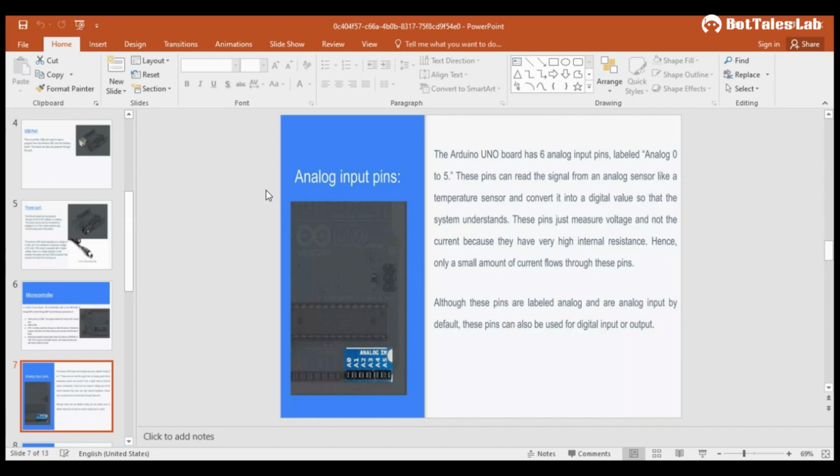input. That is, some sensors are there, like a temperature sensor or gas sensor, which provide output, or you can say which provide data in terms of some particular value, in the range of 0 to 255, in the range of 0 to 120. While other sensors are there which read data in the value of 0 or 1, or you can say low or high. But you can't connect a sensor which reads a particular value into a digital pin. A digital pin only provides sensor data in the format of low or high.